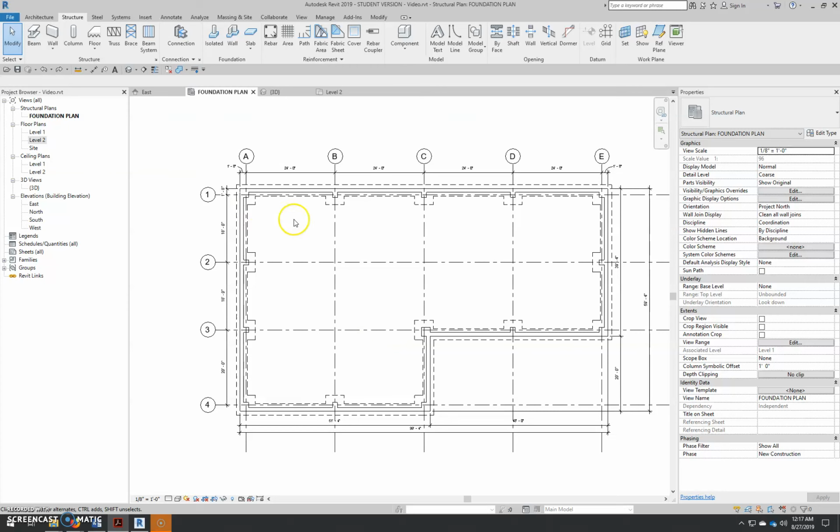Alright, so I've gone ahead and I have all of my footings for all of my piers in place now. The next thing that we're going to do is get the internal columns set up. So at the intersection of B3, C2, and D2, we have concrete columns. We do not have a dimension given for those, but they appear to be the same size as the piers.